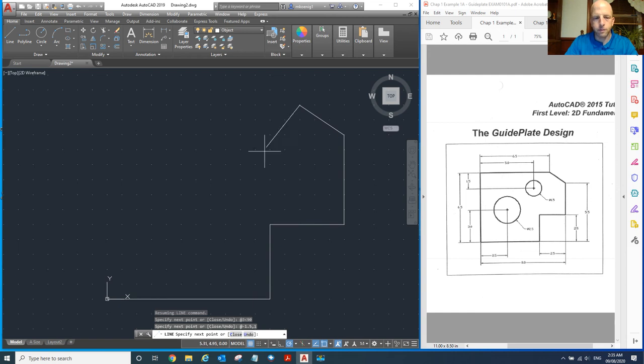So we did absolute, relative rectangular. This line was snap to grid, interactive. This line was relative polar. This slant diagonal line was relative rectangular. Next we're going to do a direct distance entry.